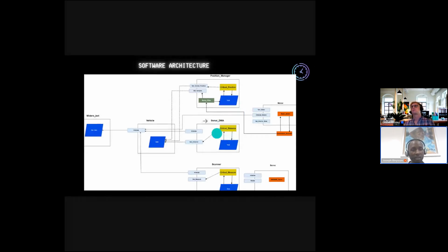The position manager has a noise filter, which you can see here. This feature acts as a recursive moving average, so it smooths the digital signal coming from the sensor. What sensor? The quadrature sensor coming from the motor over here.